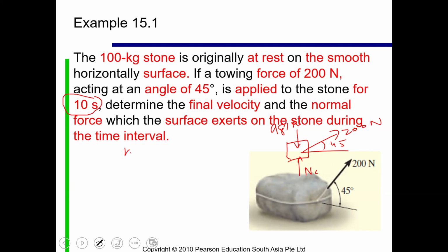So students, now we need to put the formula: mV1 plus the sum of all forces and the time interval is equal to mV2, right? And you know that this is a 2D problem, so we need to use it for the x-axis and for the y-axis. When I write first for the x-axis, think of rewriting this equation for the x-axis with velocity information in it. I'm saying that velocity is positive in the positive x direction. So what should I write for x now?